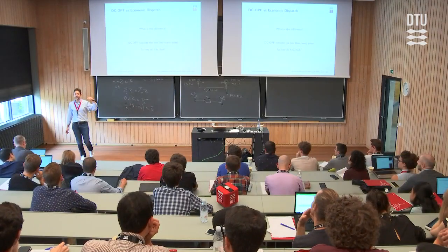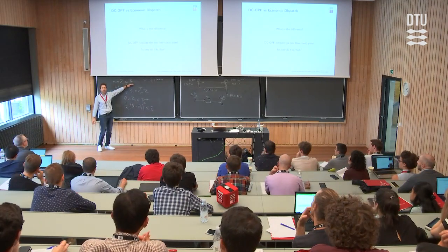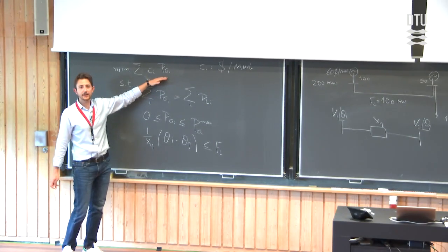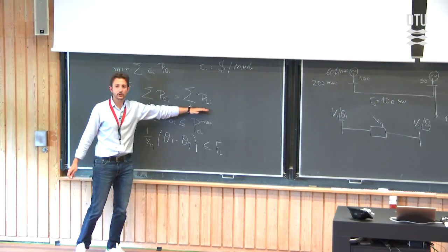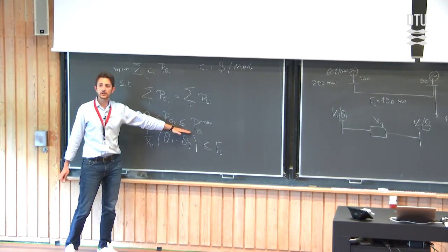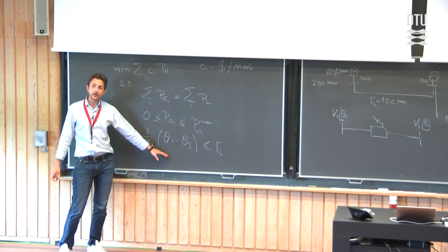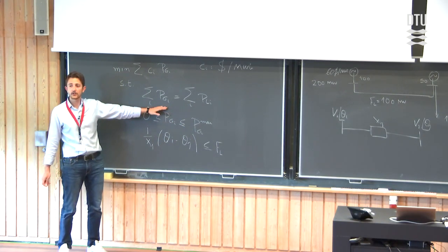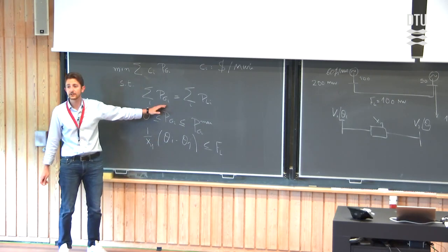If you think of it as a system of equations, I have an optimization. I'm trying to minimize PG. That's my only free variable, and because it's in the objective function, it's going to find something that actually minimizes that. And this free variable must be equal to some constant and must be between these limits. But now I have the thetas. If these thetas are constant, then I cannot move anymore with my PG. If these thetas are free, they are too free.